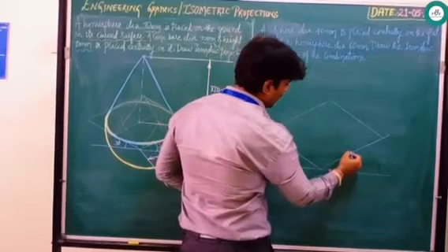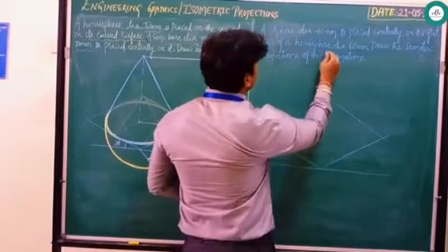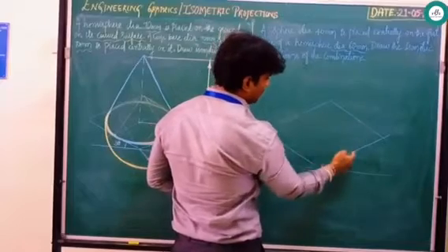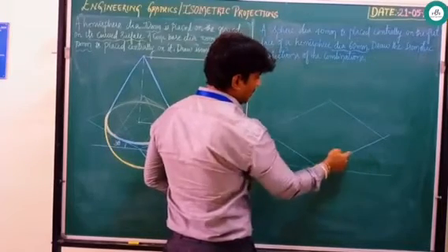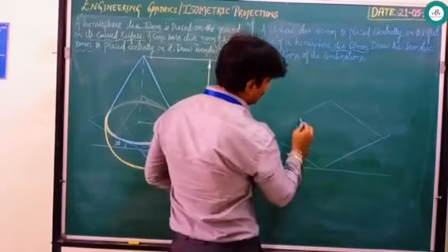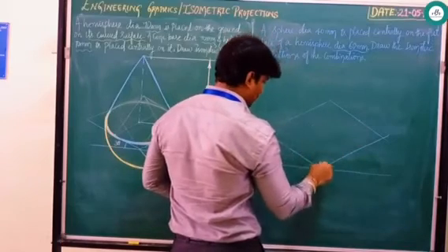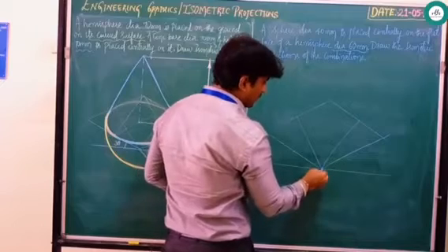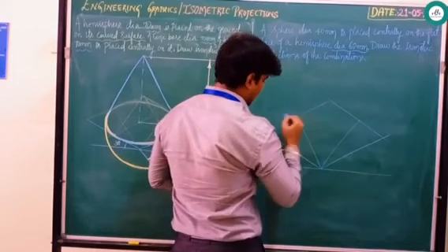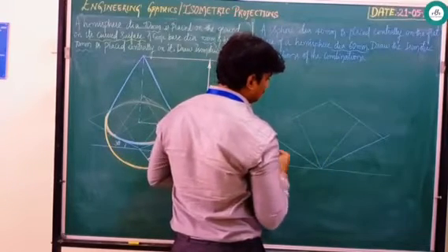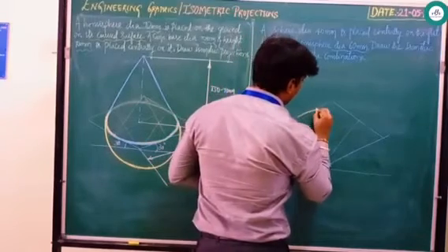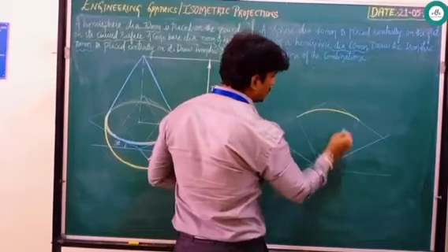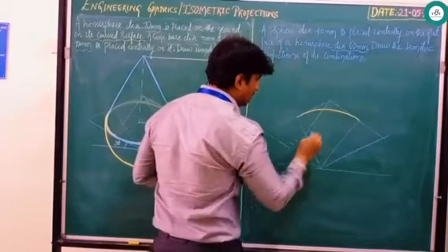After that, identify the opposite point, same as in the previous problem. After identifying the center point, since the hemisphere diameter is 60, these points will be placed at the center, that is 30. Next, after placing this, join these two points to this particular point. After joining, with this as a center and this as a radius, draw one curve this way. Next, similarly, join these two points to the opposite one.